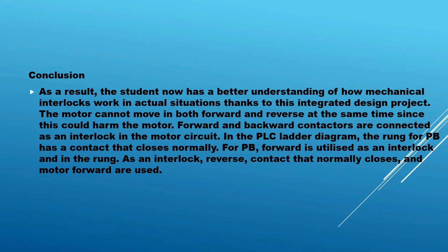Then our conclusion: as a result, the students now have a better understanding of how mechanical interlock works in a real situation thanks to this integrated design project. The motor cannot be moved in both forward and reverse at the same time since that could harm the motor. Forward and reverse contactors are connected as an interlock in the motor circuit.